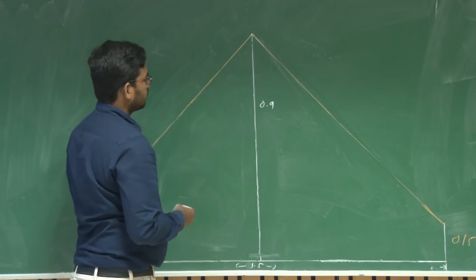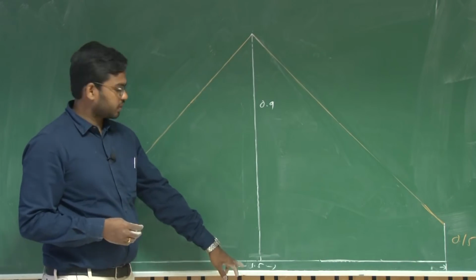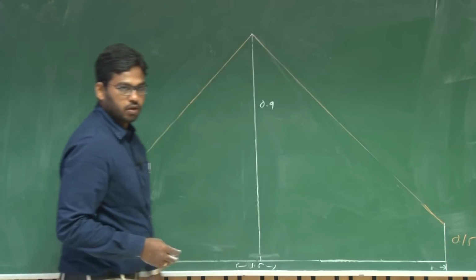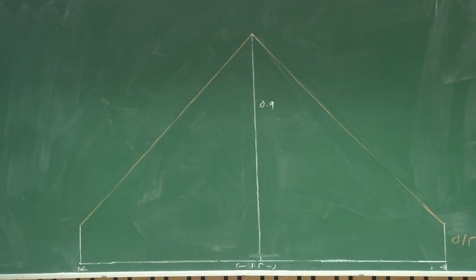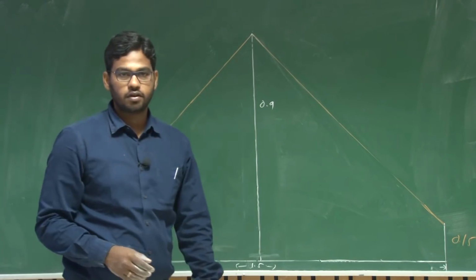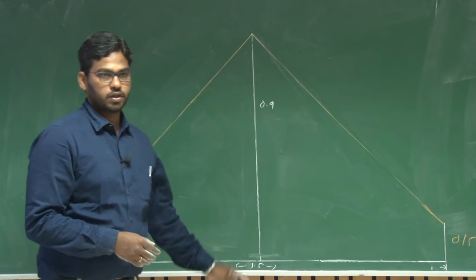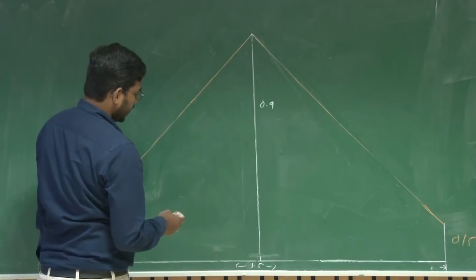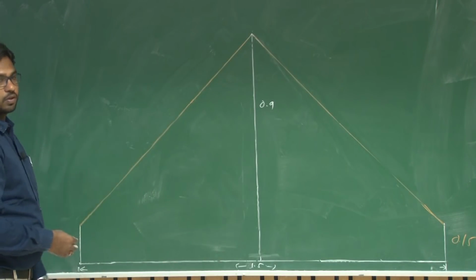Okay. So, tapered is about the trailing edge, that means the trailing edge of the root chord and the trailing edge of the tip chord should lie along the same line. So, this is the planform geometry, and we will show the flight test of this particular design, this particular UAV. Now, what should be the mean aerodynamic chord of this particular planform?